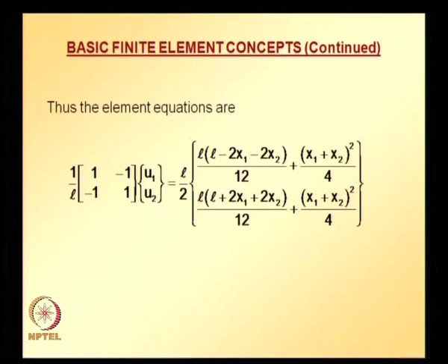Now, plugging in what is K, what is D, what is R, these are the elemental equations or element equations for a typical element of which x equal to 1 is not a part. That is why, in the beginning, we have written element equations for an element without applying the boundary conditions. Why I am doing this will be clearer to you in a while. Now let us develop the equation system for an element of which x equal to 1 is a part.